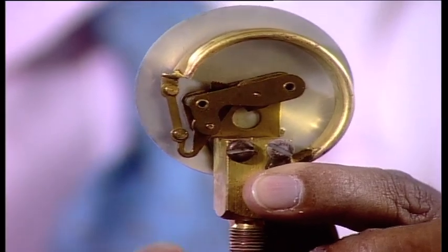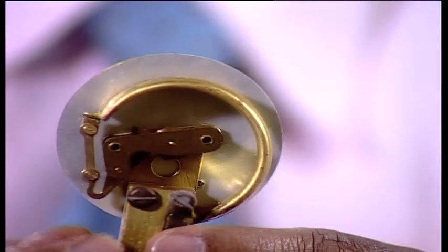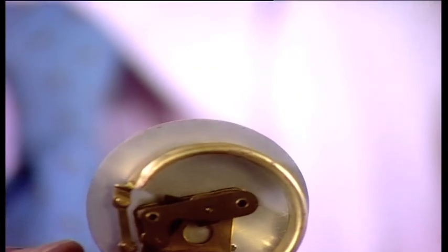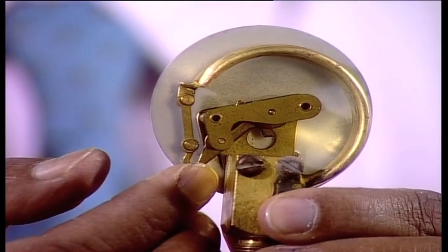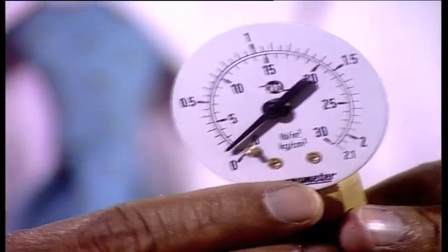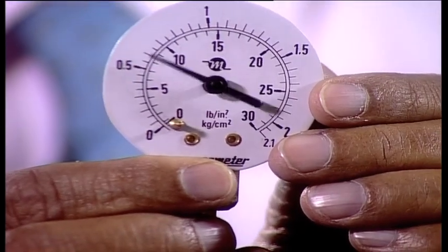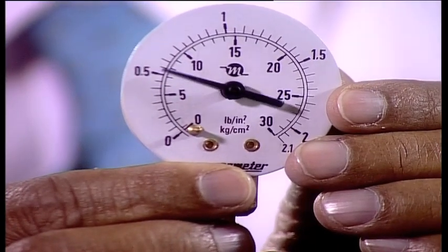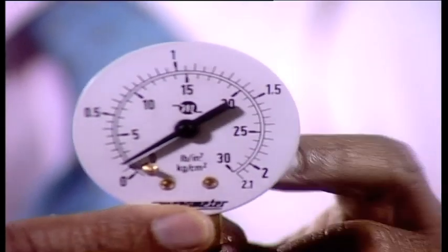The sector is here. Now, what will happen, if I move this, because this tip will move outside, is it not. When the pressure increases, it will move this way. The sector will move, and there is a hairspring. Again it comes back to the original position. Now, again I am telling, at atmospheric pressure there will be no movement, but if I increase the pressure, you can see here.